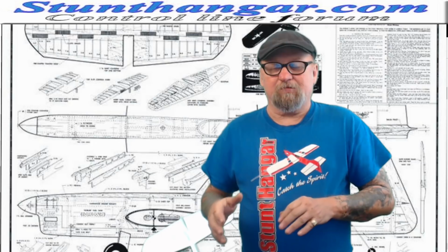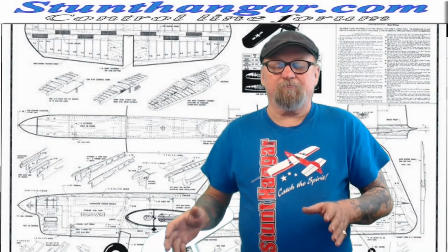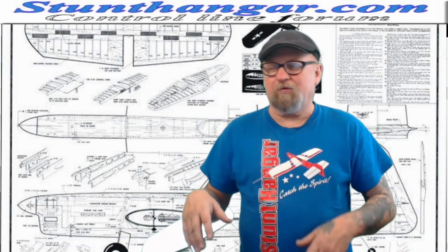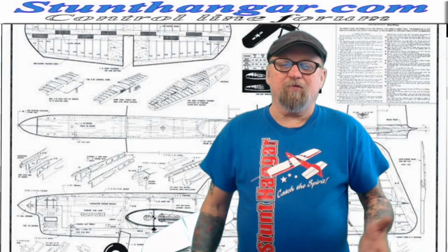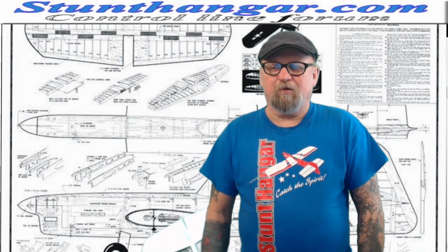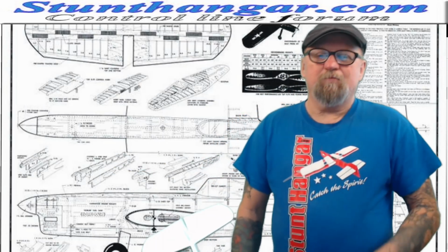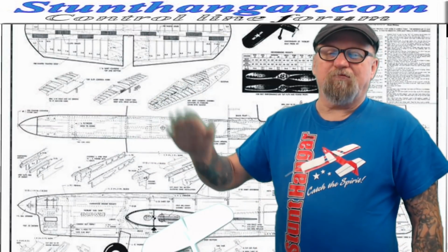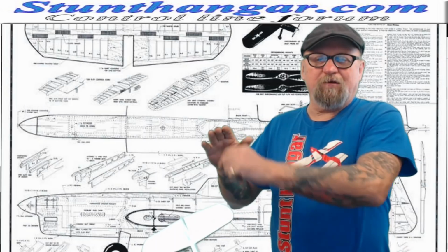And what this does is the longer inboard wing, you think, well, it's going to cause it to lean in. Well, no. The longer the inboard wing, the less wingtip weight you have to put on the outside. And you say, what do you mean the less? Because it creates lift. It's creating more lift to offset the weight of the lines.